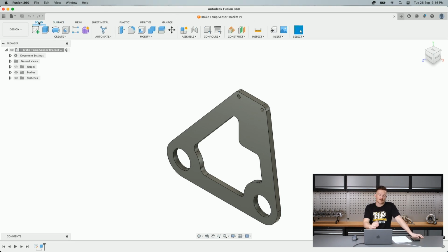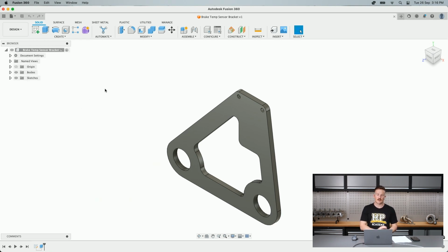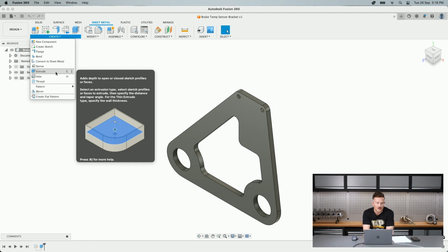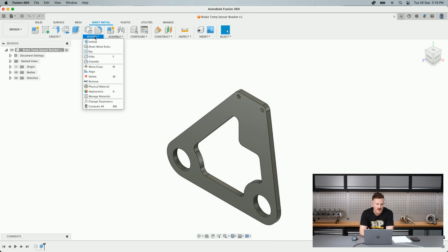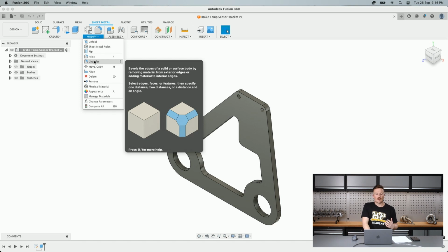And solid is where we generally work if we're modeling something that will be machined, for example, on a whatever axis mill, something that will be machined or lathed, or a plastic part, something we're going to 3D print maybe. We're generally working in this area here with these tools. And just as something to remember, you'll notice here that these tools are shown in blue, because we'll see some of those in a moment under our sheet metal modeling tab. So if we jump over here to our sheet metal tools, we still have some of these same blue tools here, like extrude, for example, the hole tool, create sketch. Some of those, and under modify as well, we also have fillet and chamfer. And they're all tools that we use in our solid modeling as well.